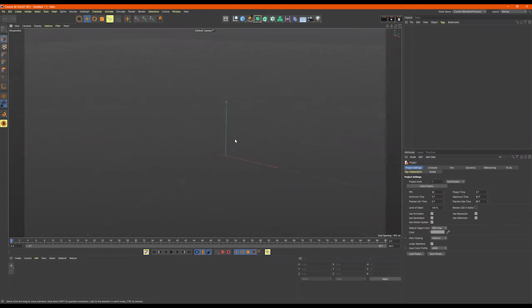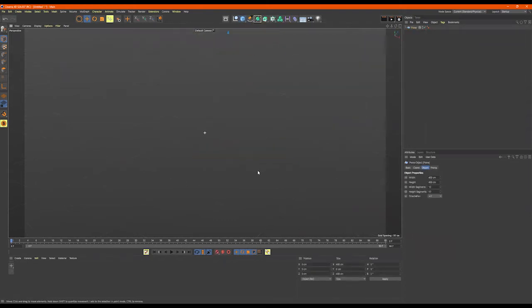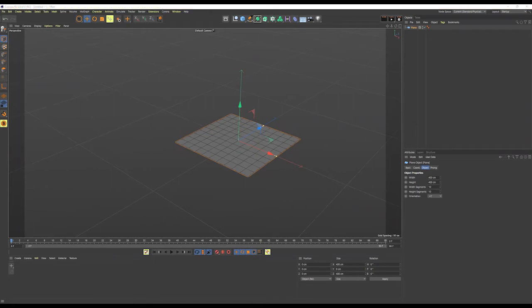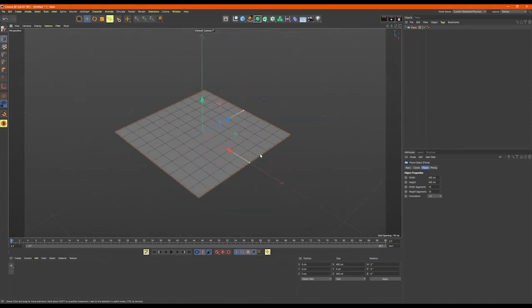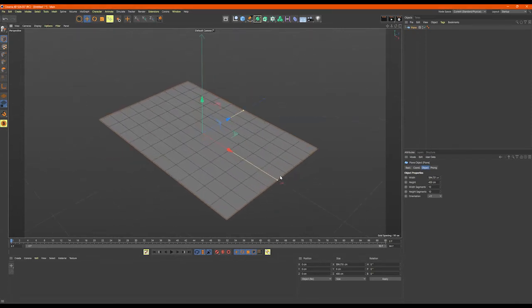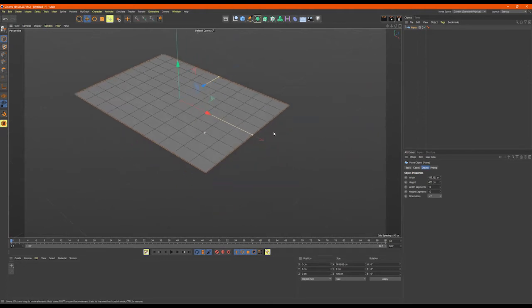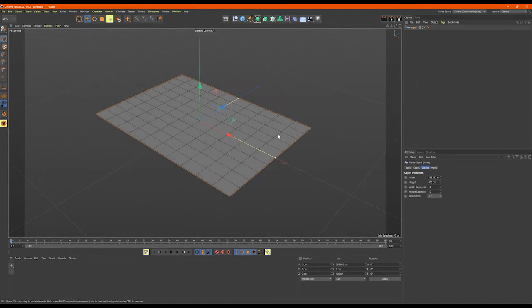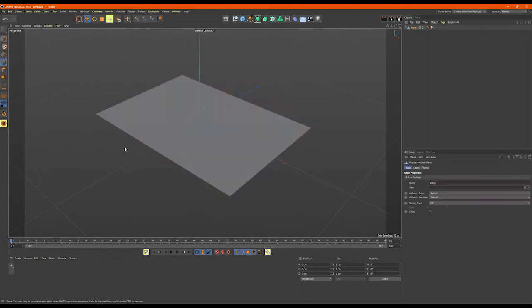All right, isometric room, Cinema 4D. So let's first start off with a plane, right? Just S to zoom in, and B. All right, I'm going with a slightly different layout, but it's still going to be an isometric camera. So I'm going to go like this, start off with the grid, C to make it editable, get some edges.